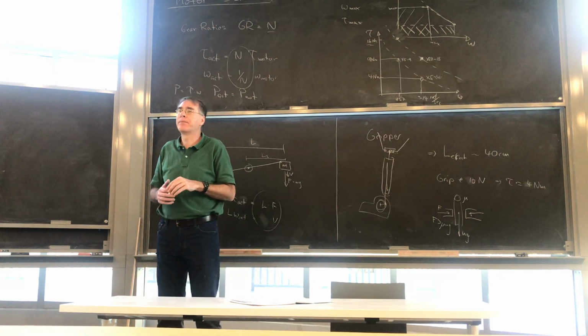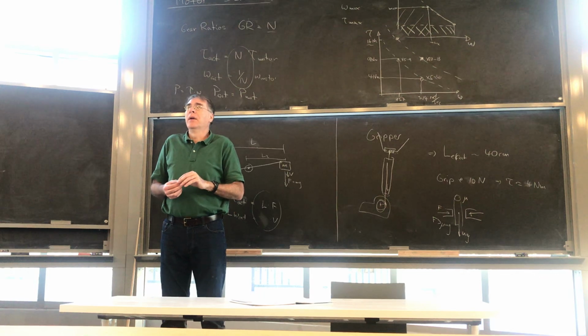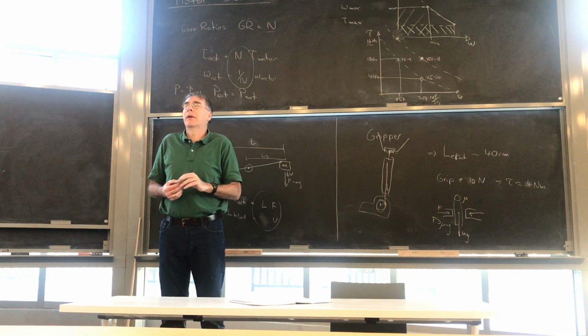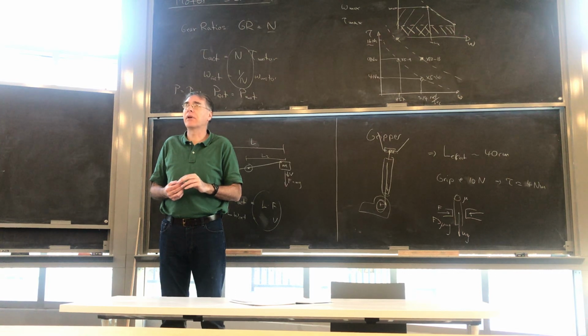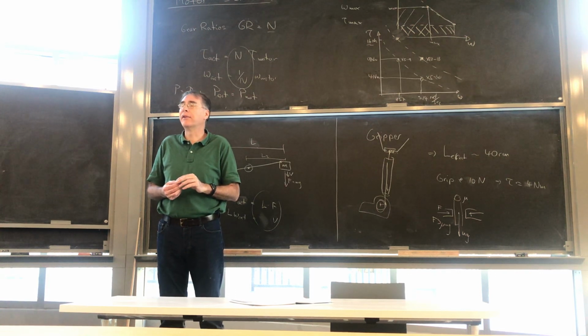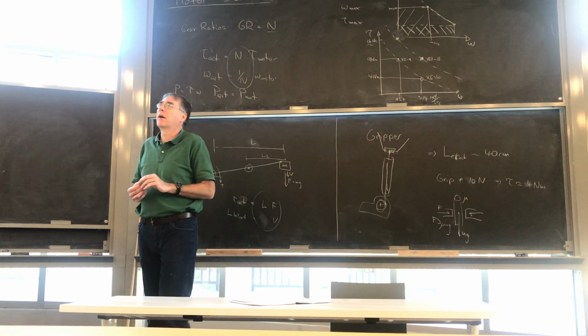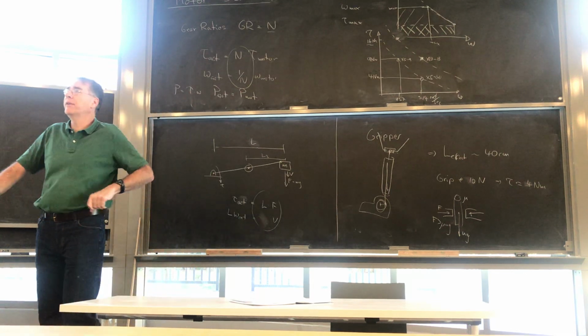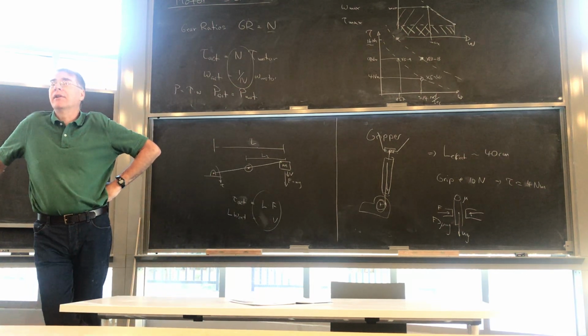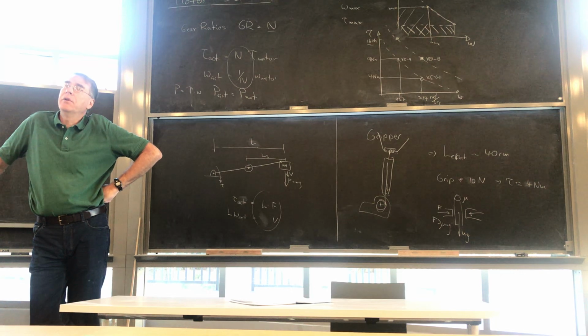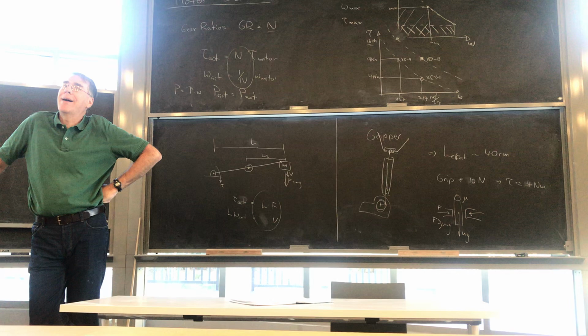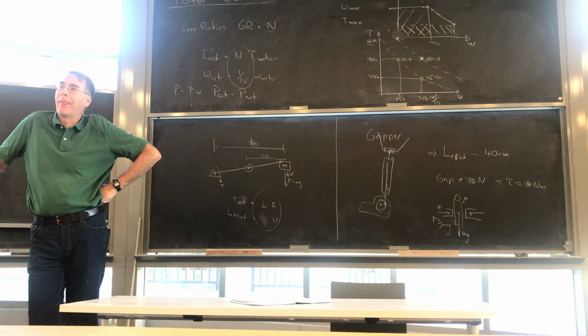But yes. Will it tell you where it's going to cut you off? Does it report what it calculates its maximum to? I think if you dig through it, it gives you the current temperature so you can tell how close it's getting. So does it tell you, I will let you come in this much, or do you have to figure that out? I don't know, I have not tested this. My guess is that it's abrupt, that it'll give you the continuous torque until it decides it's too hot and then it'll just take it away from you. So it won't ramp it down, it'll just suddenly take it away.